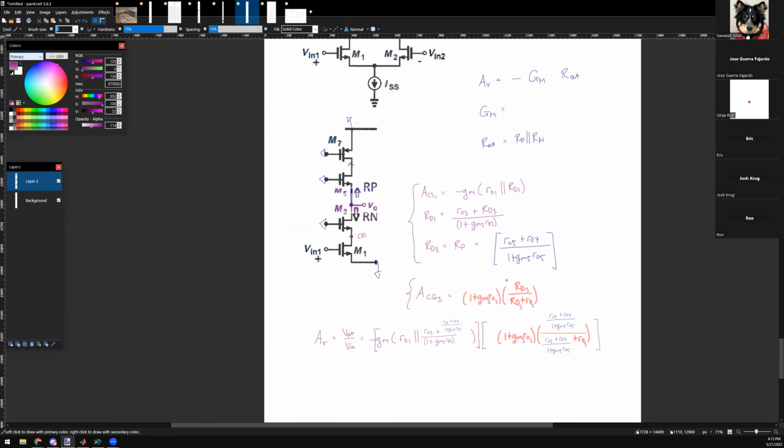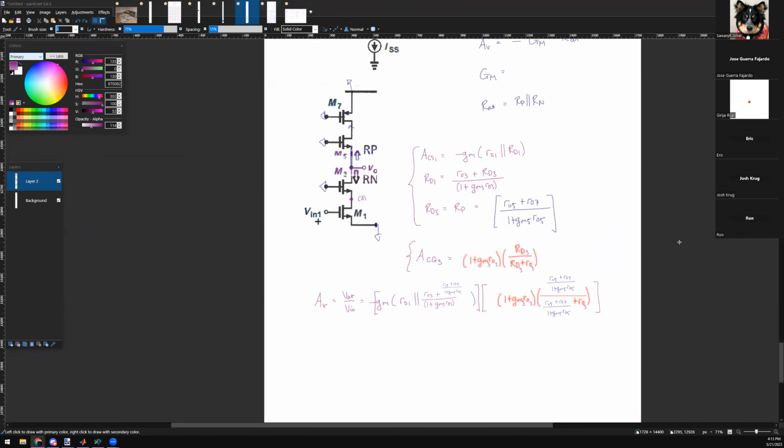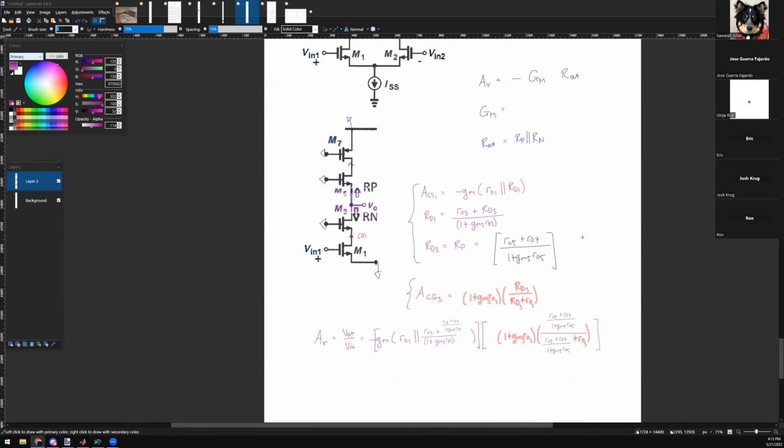This circuit he's using for explaining all the concepts, but he always uses one generalized equation for finding the gain, like R_op parallel R_p parallel R_n, and then he goes with that. That's all. But he doesn't really simplify for R_p parallel R_n. Yep. So, any other questions?